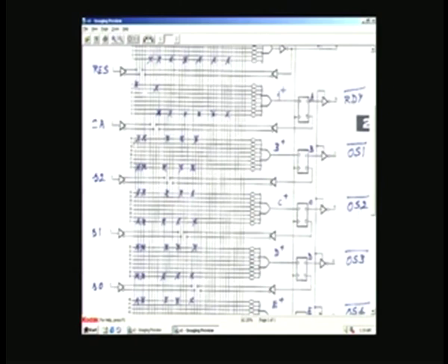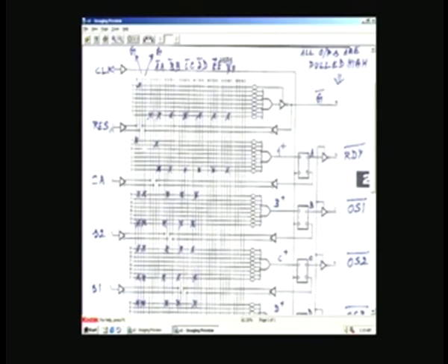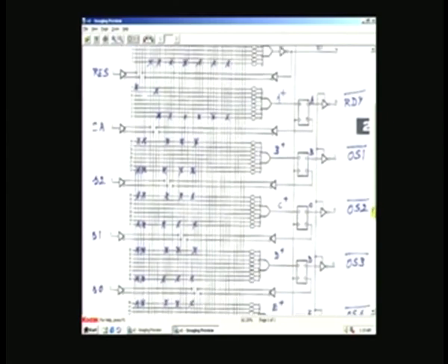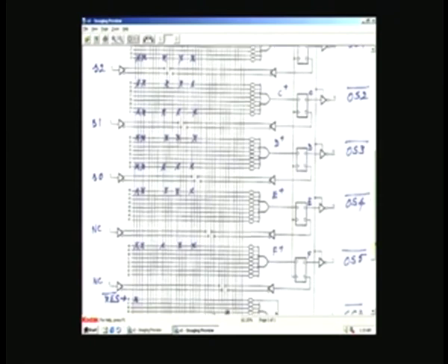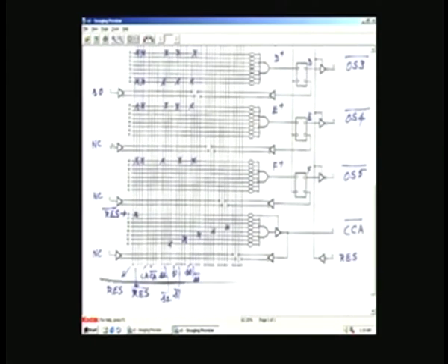And the inputs are of course as you have seen earlier: we have shown the reset input which comes from that Schmitt trigger, the RC combination. The clock is given to the first pin, then the S1, S2, S3 inputs and no connections. The other connections are not used. NC means no connection, we are not connected. These three are not connected.